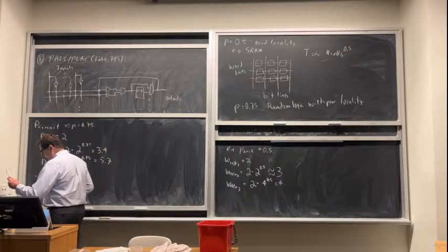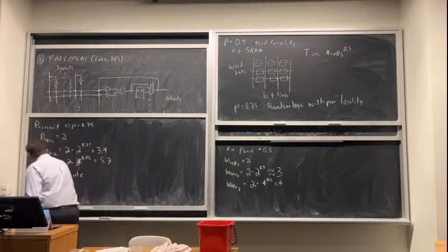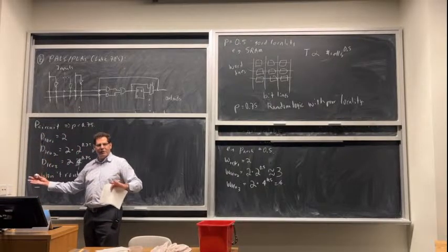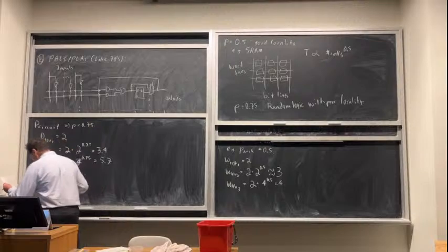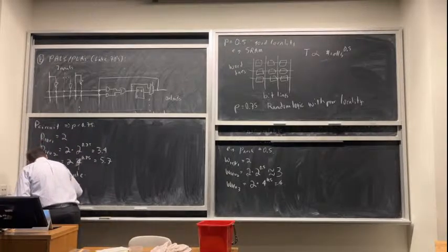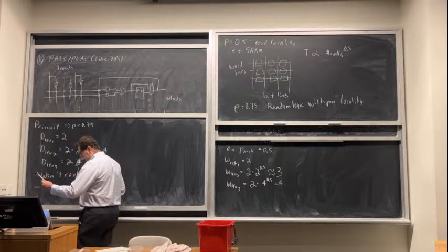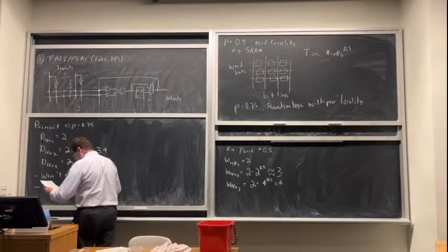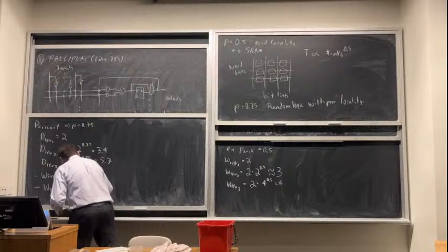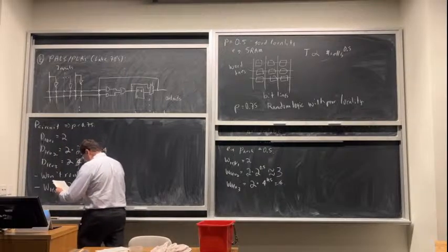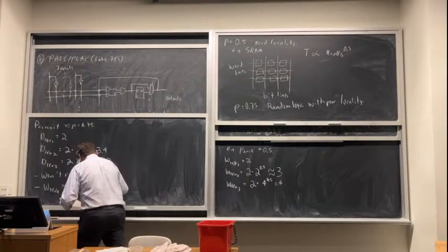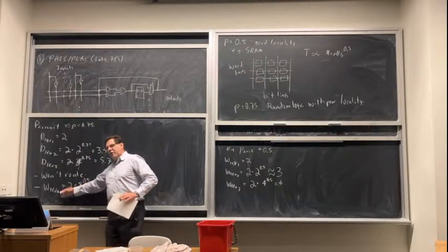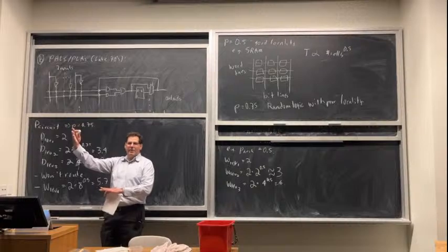So if I move them to a bigger chip, let's say a chip that instead of 3 levels of hierarchy has 4 levels of hierarchy because it's twice as big. At level 4, okay, so I needed to buy a bigger chip to get this. The number of wires I have is 2 times, the amount of logic I have is 8 times the base level. My rent exponent was 0.5. If I put all that together, I get 5.7 wires at level 4. So a bigger chip will have a routing channel big enough to handle this. It's 1 level higher in the routing hierarchy in this case.